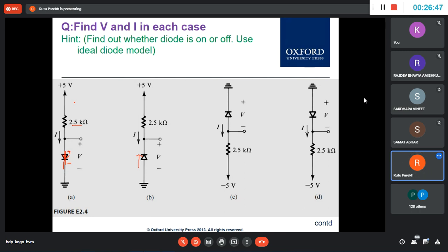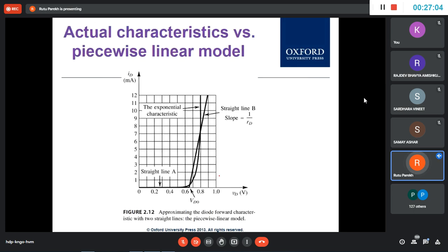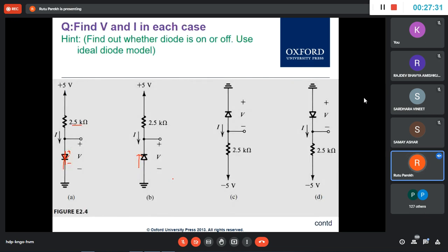And always remember, when the diode is conducting, the current is in the range of milliamperes. You can see the exponential graph that we had seen right here. This is your current, always in milliamp when it is conducting, right after 0.6, 0.7 volt. But this region before conduction is somewhere in micro, and then this is in nano, although some current is always flowing, in nano or picoampere. So once you get an answer, you should know that it is in milliamp. Don't forget the unit: if the unit is wrong, you will lose the mark.